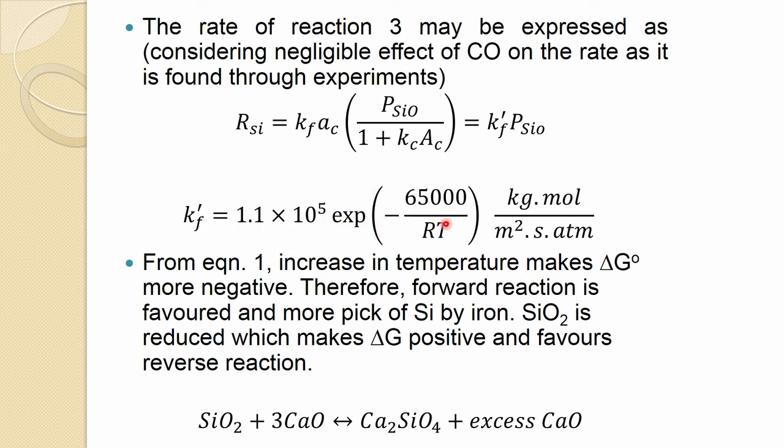But this is again an experimentally measured and established value, and it is used when your carbon percentage in iron is about 2.8. For saturated 2.8, 2.9, this is in the blast furnace when it is dripping down, but for a saturated carbon melt there is a different rate expression which can be found.